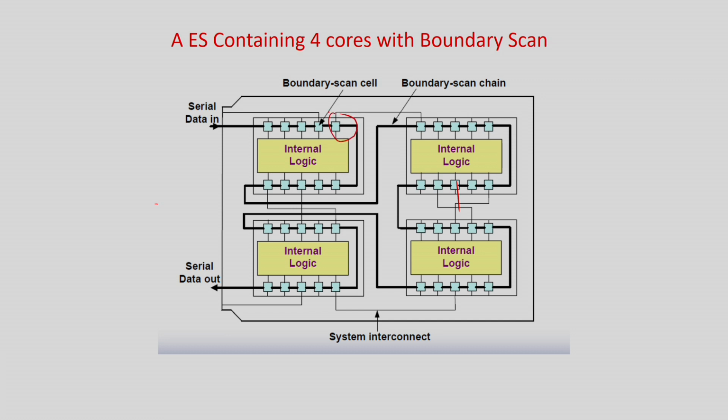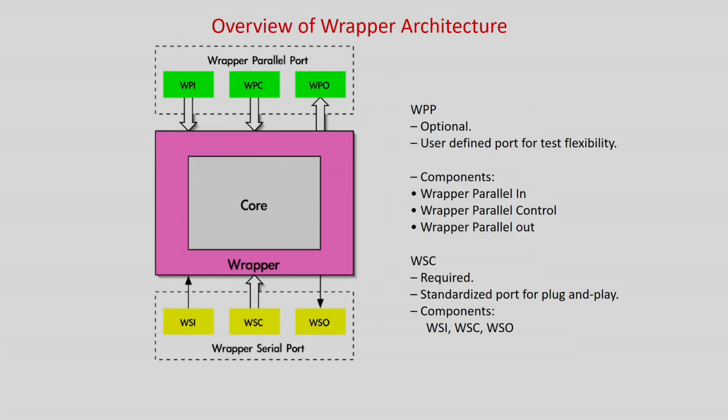I will elaborate how it looks. It is nothing but a simple scan register with slight modification, of course. So this is a wrapper, and this is the core. As I told you, this is not a PCB kind of design; it is a chip which will finally be fabricated. So we should always try to follow a particular design protocol, and it is the IEEE 1500 standard. So the core, and of course as I am manufacturing a chip, I make it IP protected, I have to sell it.